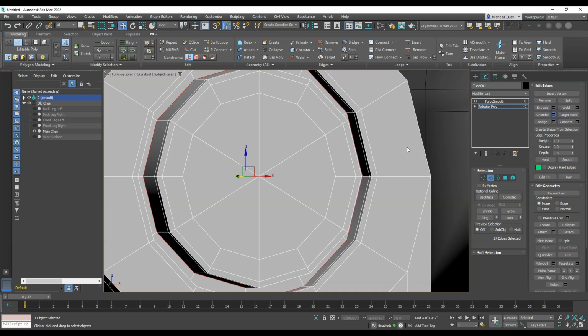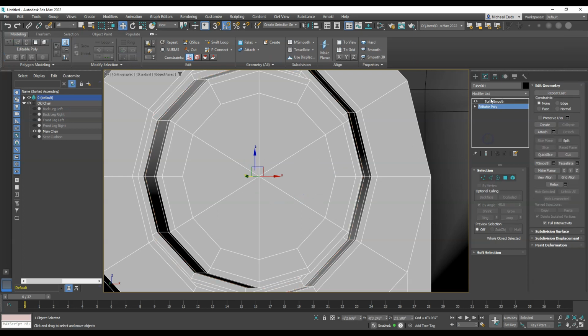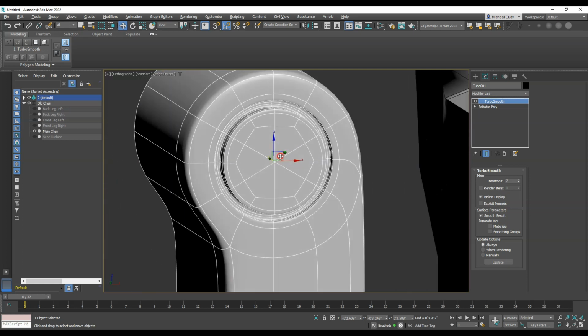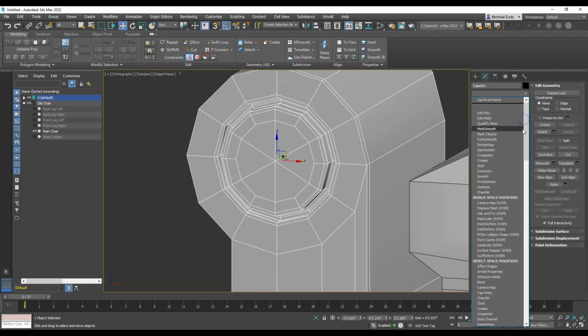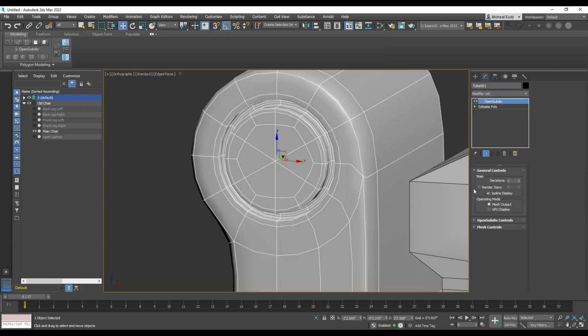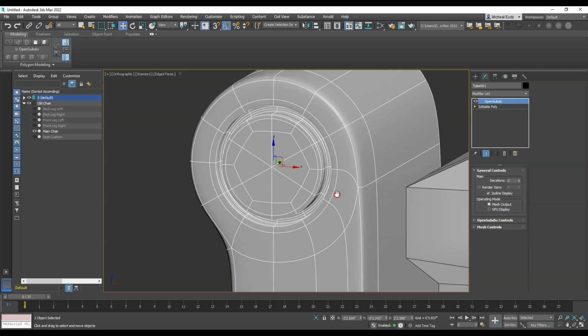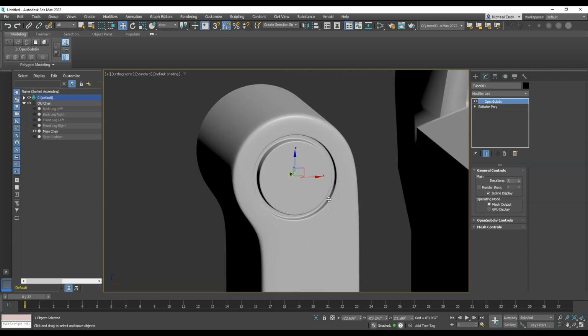The chamfer modifier will keep the last settings, so we can just pull that in and set it in. It'll have the same settings. Okay, so now that'll keep that inset on there. It'll need 3 iterations. At this point, let's switch back over to an open subdiv so that it's exactly what Maya would use in Max Subdivision. That way they're both exactly the same.